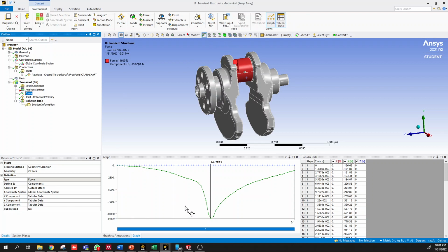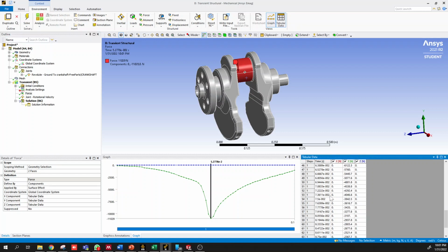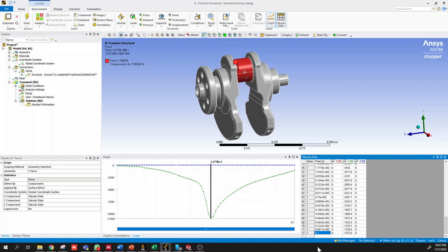So we have a time varying load signal. The data here corresponds to every 5 degrees of crankshaft rotation, and there's 360 in total. So we have 72 data points ending at 0.1 seconds, which is 10 hertz, or effectively one cycle every 1/10 of a second.